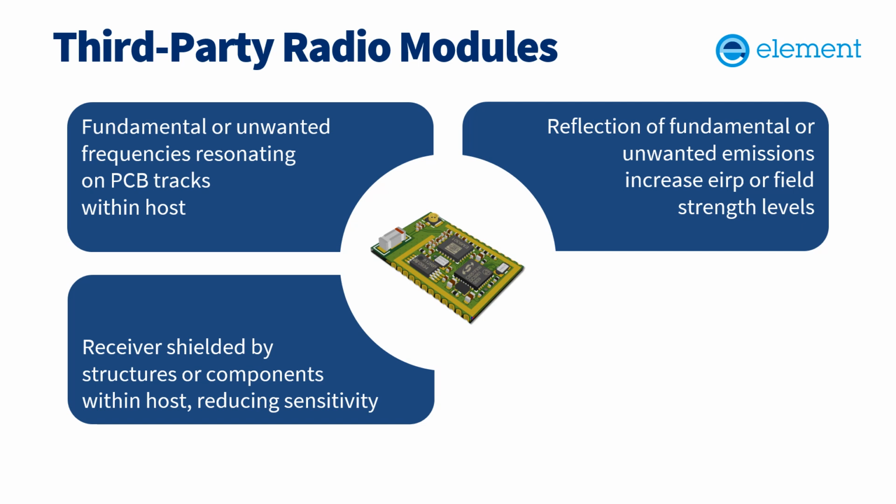Inversely, if you took a radio receiver module, for example, and embedded that into another piece of equipment, it might have lots of metallic surfaces around it, then it might block some of the signal and effectively make that radio module more deaf, which will then affect its sensitivity, its ability to receive the signal.